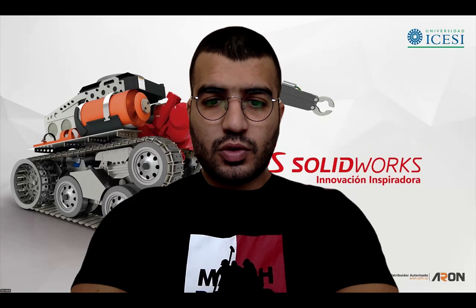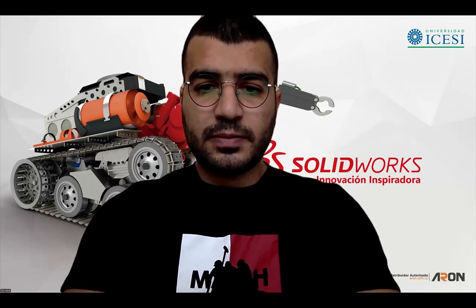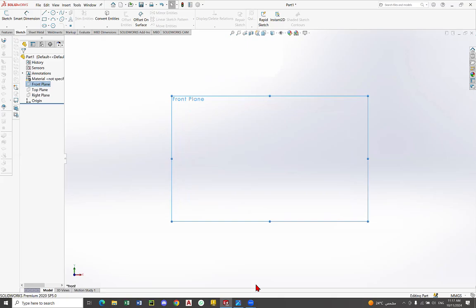Today, we will continue the tutorial by creating part 4. So first of all, we should open SolidWorks. Okay, we should check that the units here are in millimeter, gram, and second, not in centimeter nor in inch. First step. Second step, choose the plane that you want. Right click, normal to, for example, on the front plane.